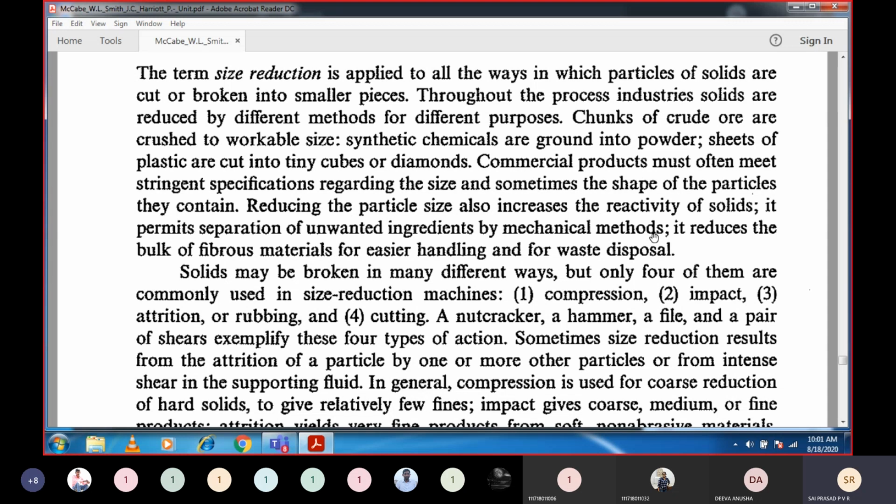Non-magnetic materials are thrown up. Imagine you are keeping a lump. So what will happen? The lump will be attracted because it will have magnetic material and non-magnetic material also. And by default, what will happen? The magnetic material will be attracted to it, and since it is in the same mass, even the non-magnetic material also comes out. So we cannot ensure proper separation there.